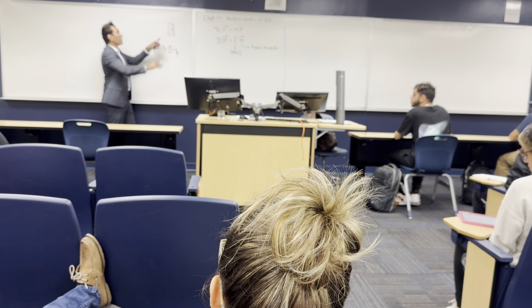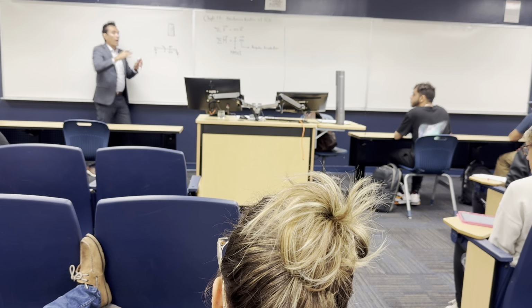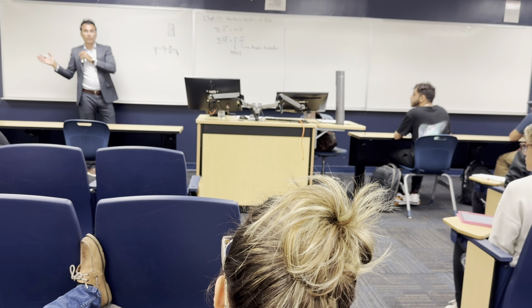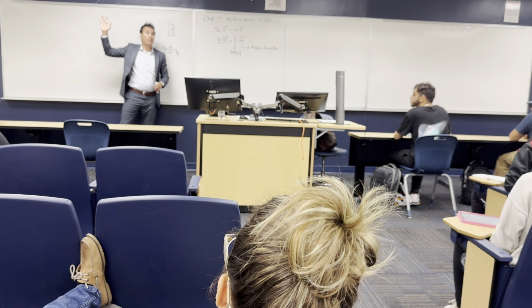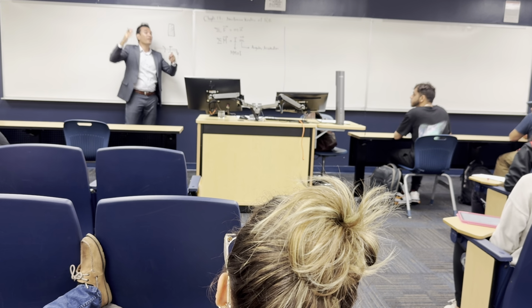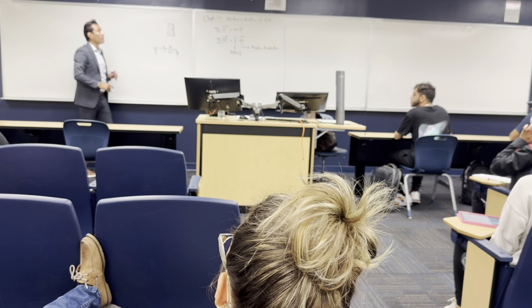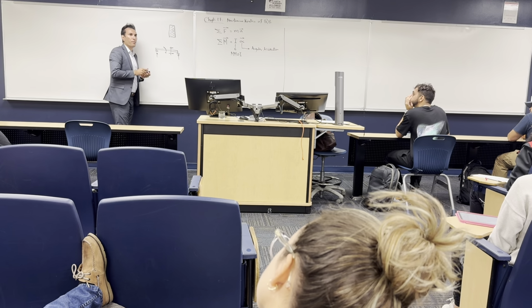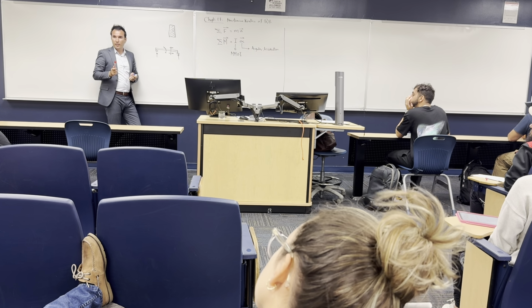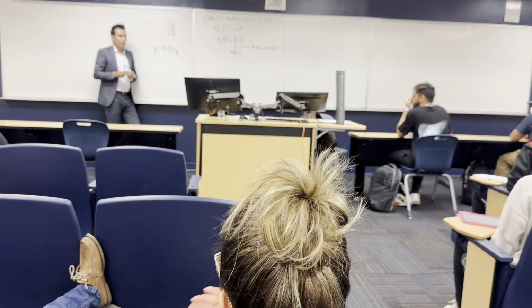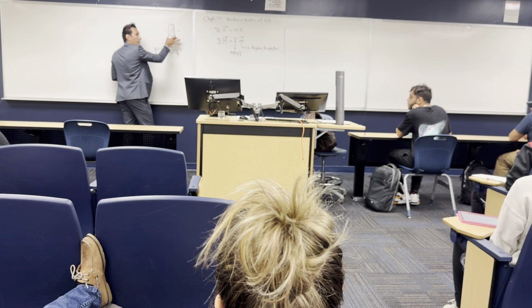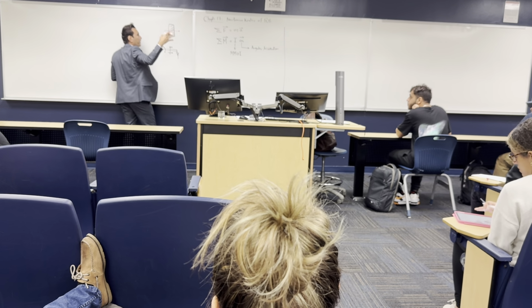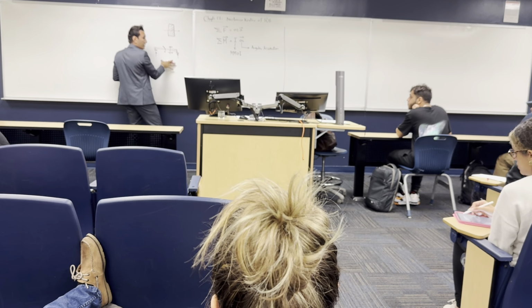Let me ask you, if the area of the cross section gets bigger, what will happen to the area moment of inertia? It's going to get bigger, right? Say this floor is supported by a beam, and I found that this beam is going to fail with the original loads, so I need to increase the cross-section area. But let me tell you something. I know that you have some background in moment of inertia, from math or statics, right? This section has a moment of inertia, or what we call area moment of inertia in this context, about this axis that is different from the one about this axis.